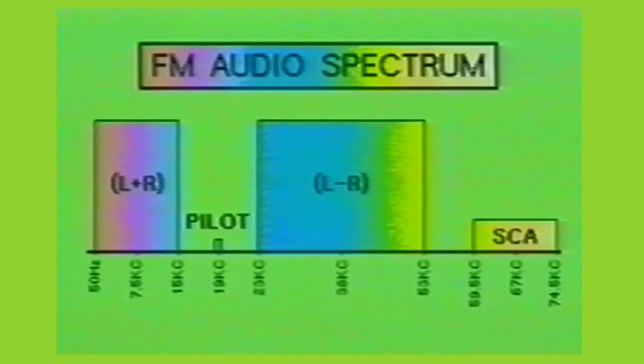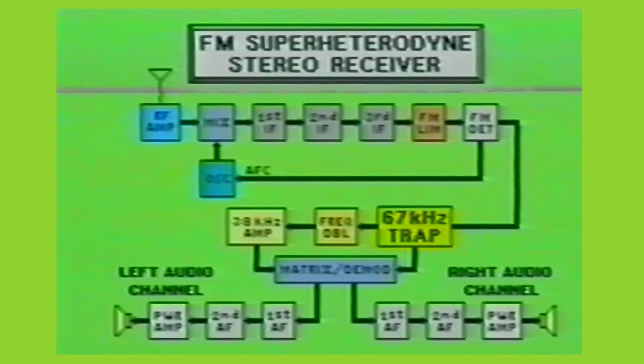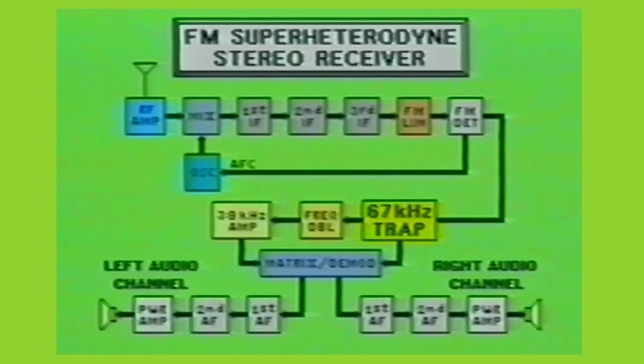If the FM station is broadcasting mono, then there will be no stereo multiplex information requiring bandwidth space, and consequently, the SCA portion of the transmission may be moved down to a lower position within the baseband of the FM carrier. The basic FM receiver is unsuitable for SCA reception because it filters out the SCA component, and the audio portion is put through de-emphasis prior to audio amplification.